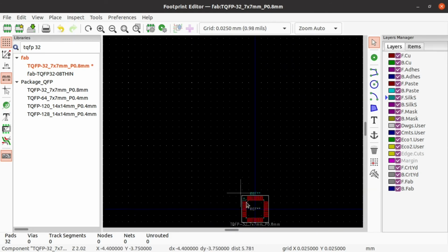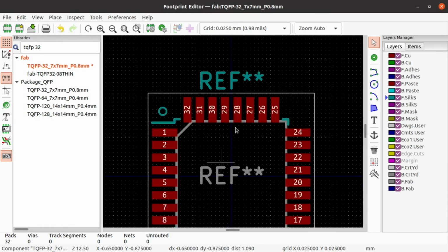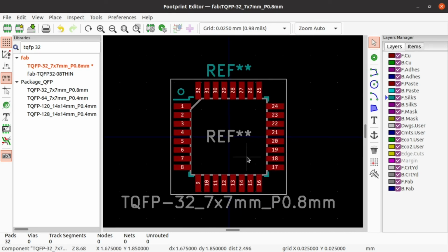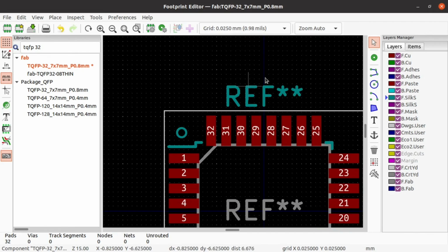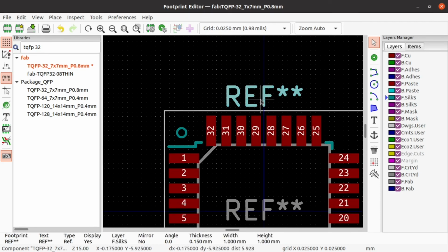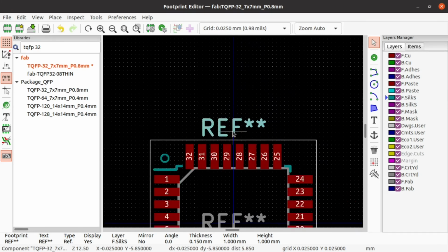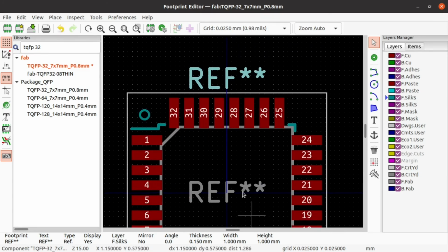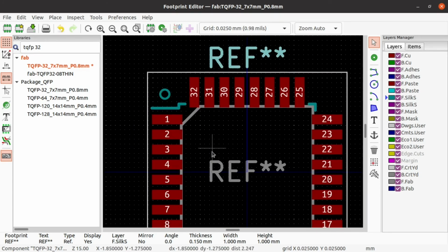So yeah, where did it go? Another good thing about reusing existing footprints is that it has all the things you need. Not all of these things are necessary for PCB milling. For example, this silk screen layer, this blue one, it's not needed, and actually in most cases it's better to get rid of it and hide it inside the actual footprint somewhere.